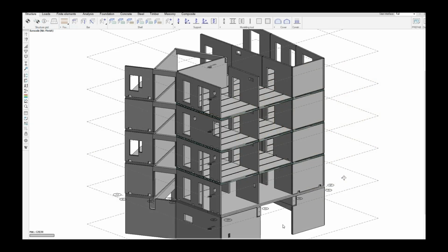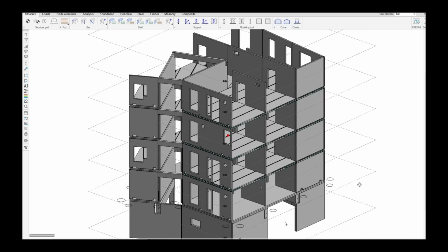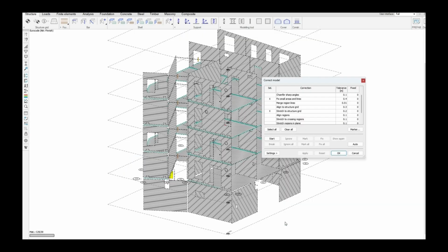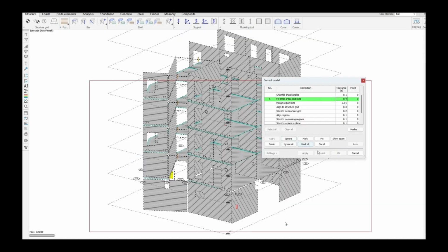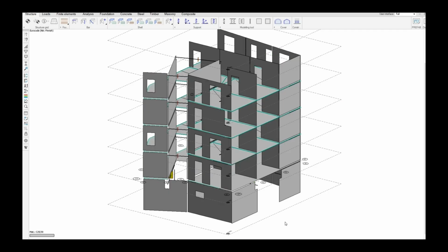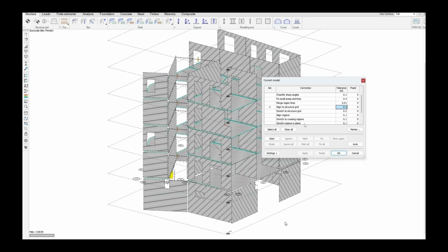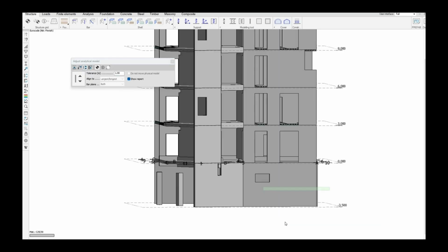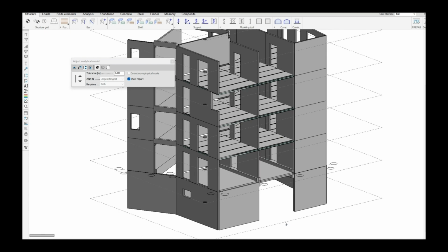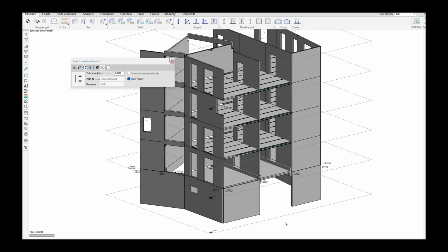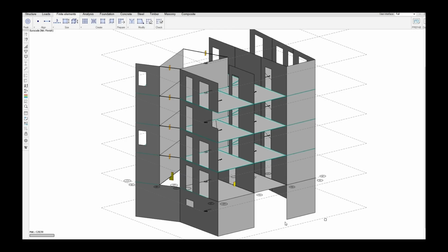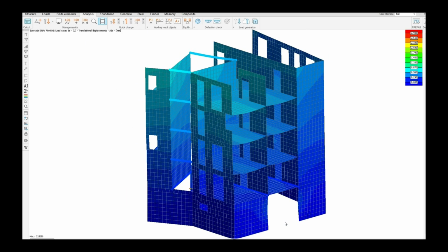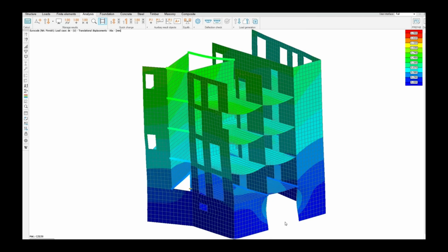So this is the demonstration of how the fixing works on, I would say, a small or medium-sized model. So we have imported the volumetric model. Then we use our correction tools. So we align the objects to masters, fix the floating point issues, align the grid, and connect objects together. And out comes the finite element model. And then we do some bigger corrections with the adjust analytical. And basically, roughly in 10 minutes or 5 minutes, this size model will be ready for finite element analysis. And we have simplified it into a pretty good finite element model.